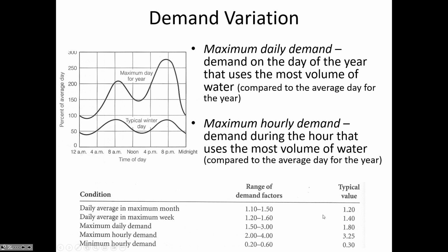So there are peaking factors that can be dependent on how big of a town you have. A city like New York City, that they say never sleeps, where people are always up somewhere, is going to have less peaking than a small town, where more people are on the same kind of cycle because there are fewer employers and less geographic distribution. So usually peaking factors in smaller communities are more pronounced than peaking factors for larger communities that are spread out over a larger area and have more variety in their industrial base and in the working hours that people keep.